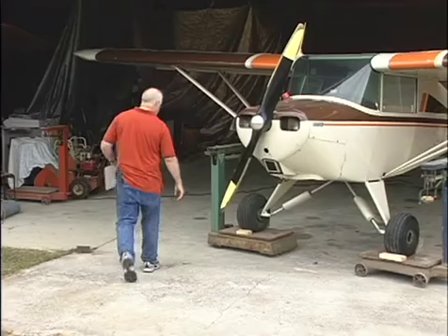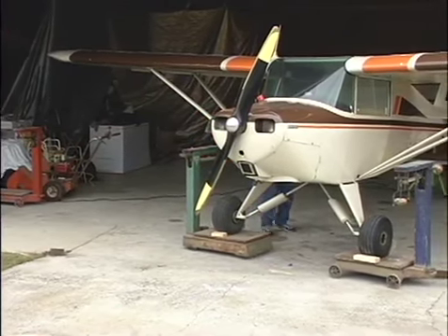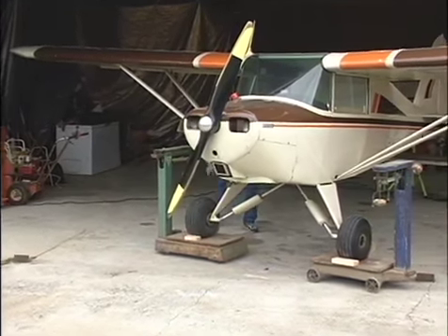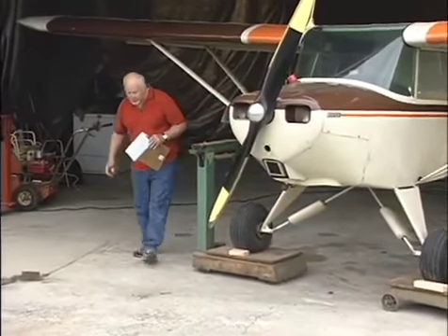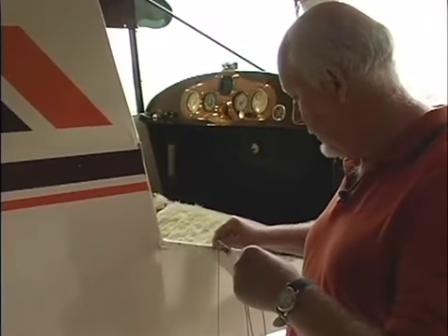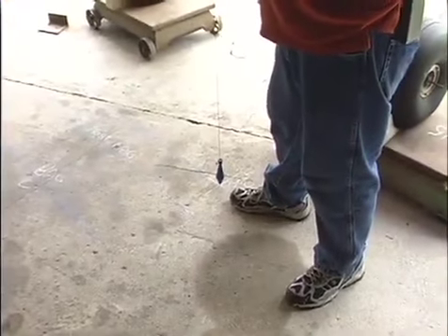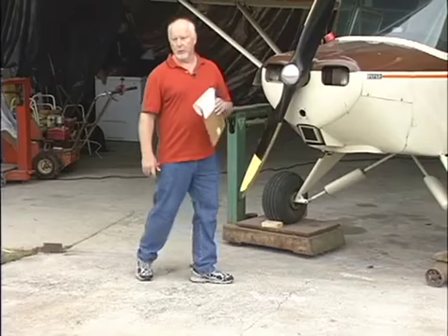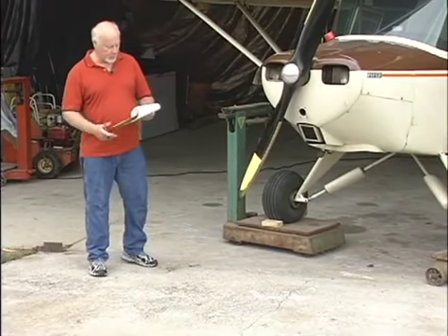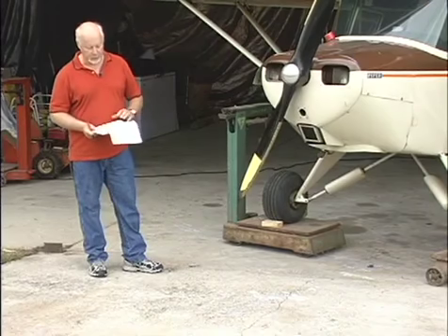The pilot seat was a fairly easy one to do on this aircraft. We just opened the door. We had a look inside, and we basically picked the part of the seat which is, as you're sitting, the back of your butt was considered the center of the seat. We dropped that line down, and we found the distance to be 74 3/4 inches back from the datum. Remember, everything's being measured from this one point. Passenger seat, this aircraft is side by side, so it's the same measurement.